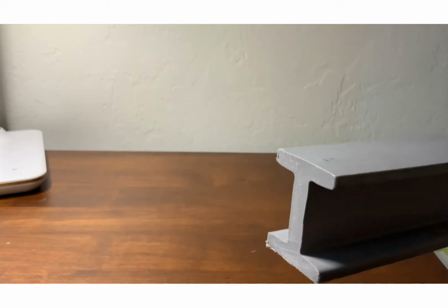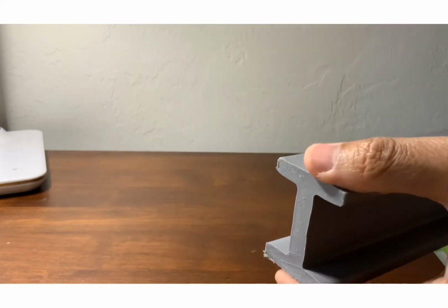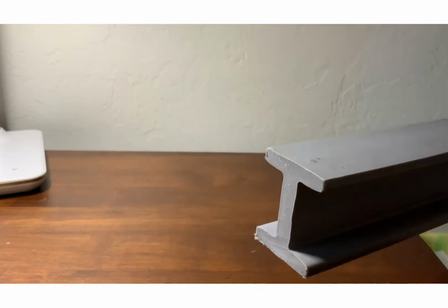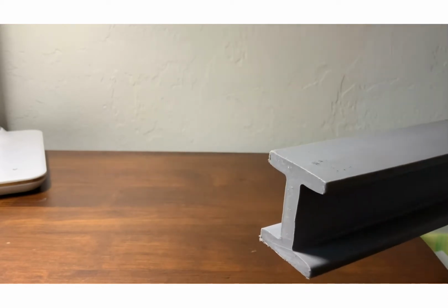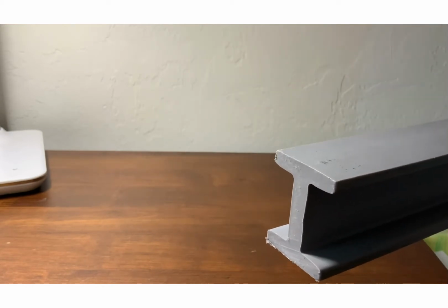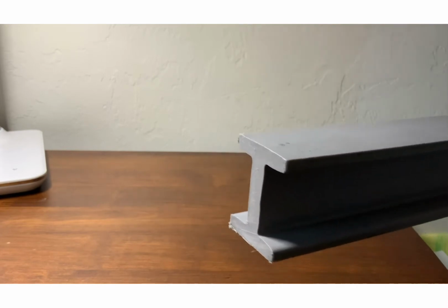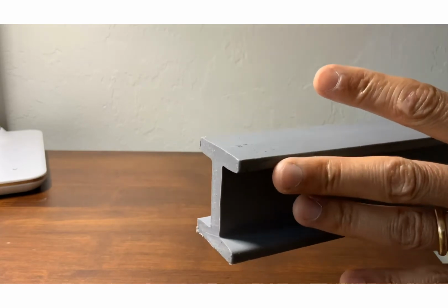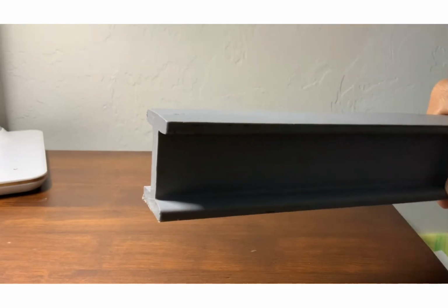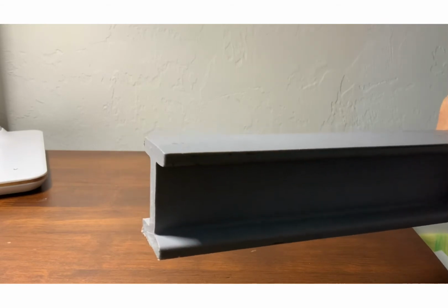What does that mean? 21 is the nominal height or nominal depth of that member, measured from the bottom flange to the top flange. The second component, 44, means the pounds per linear foot of the member. It applies the same for the SI unit,